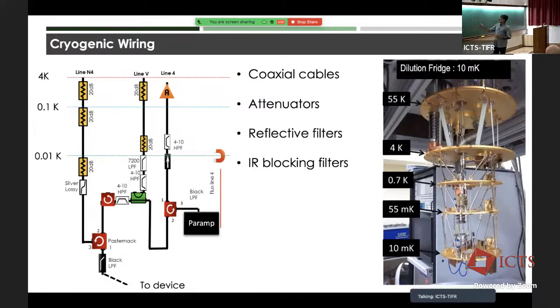And that can come directly from the hot parts of the fridge radiating through free space, like the vacuum inside the dilution fridge. So that's why we put our devices inside radiation shields, like boxes inside boxes. But they can actually also just come screaming down these coaxial lines, which are not designed for these 100 gigahertz frequencies. At those frequencies, it just looks like a tube, forms like a nice waveguide, and these photons come screaming down. So now we put some additional filters in line of these coaxial lines, which is basically some absorptive material which absorbs very high frequency radiation, so that these very high frequency photons also don't reach your device and